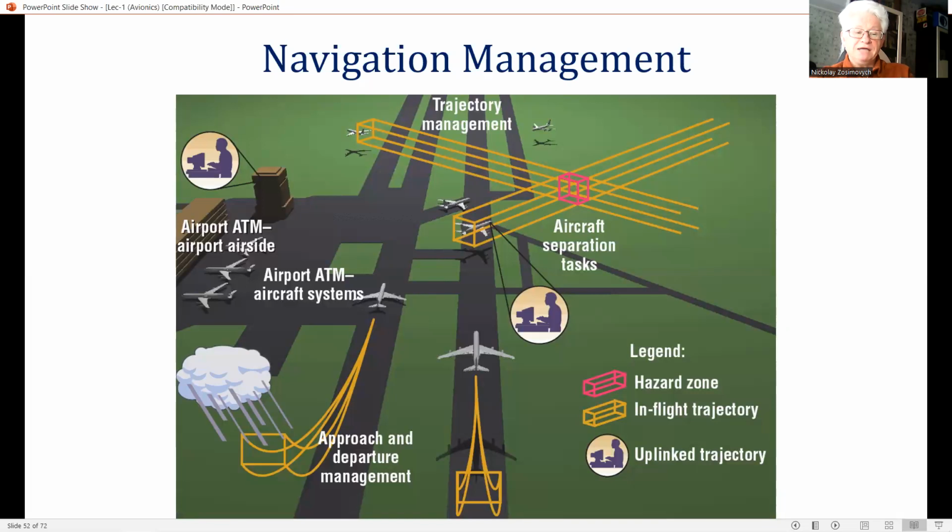Navigation management comprises the operation of all the radio navigation aid systems and the combination of the data from all the navigation sources, such as GPS and the INS system, to provide the best possible estimate of the aircraft position, ground speed, and track. The system then derives the steering command for the autopilot so that the aircraft automatically follows the planned navigation route, including any changes in heading as particular waypoints are reached along the route to the destination.